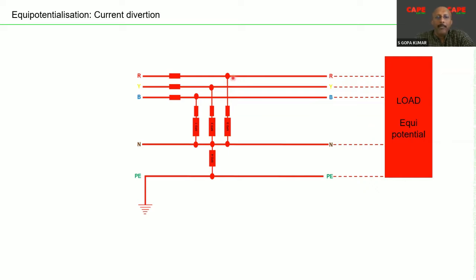The line lengths from the SPD to line, neutral, and earth shall be similar, and there is no induced part. The lightning is not going to create any induced effect between the lines. Under that condition, we have a safe installation, and our equipment is protected.